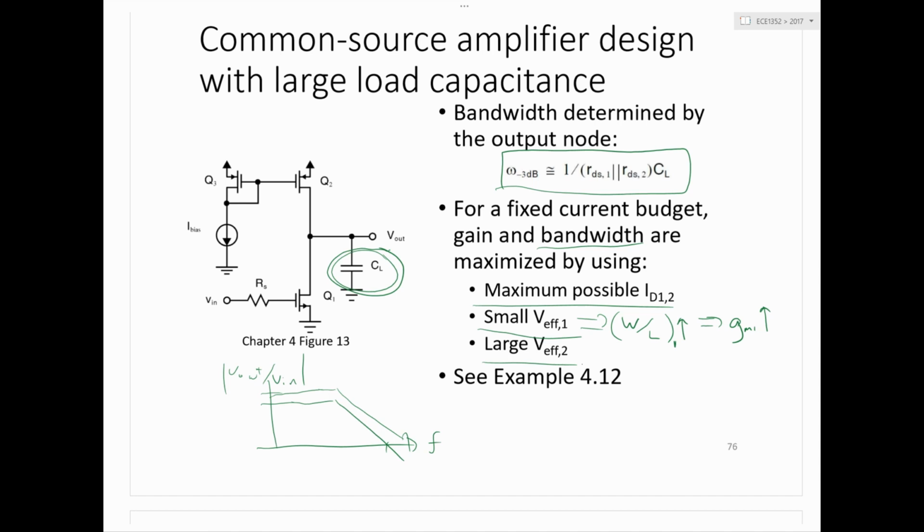The transistors that are providing the transconductance gain, you're trying to use the bias current in them efficiently, and you do that by having a small V effective typically, unless the transistor starts getting so big that it's hurting you. On the other hand, all the transistors that are not being used for transconductance gain, that are just there for biasing or as loads, unless you have time for further analysis, you would first pass assume should be biased with a larger V effective, for the two reasons I mentioned.